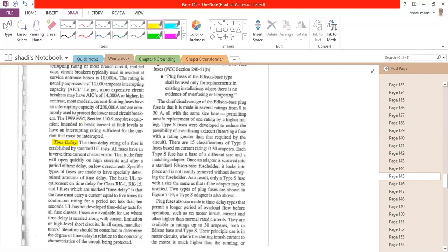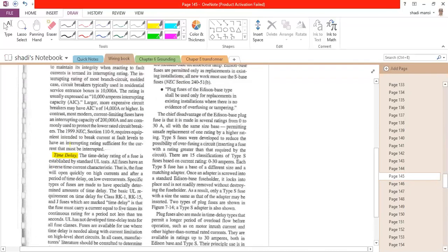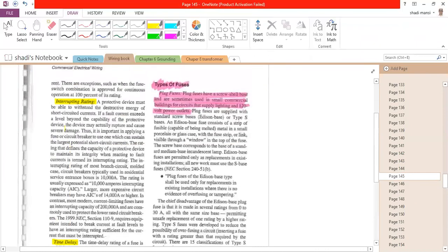Of course this is not included here, but in fuses, when we are talking about the fuse, we have to consider what the time delay is. How long does it take before it trips, how long before it opens so that the element burns. So as you can see here, we have like 4 elements that have to be considered when we are selecting the fuses.